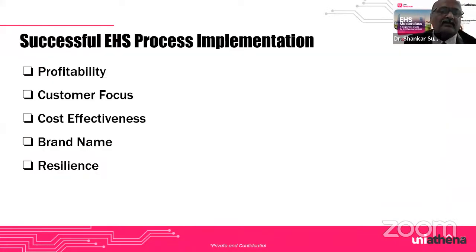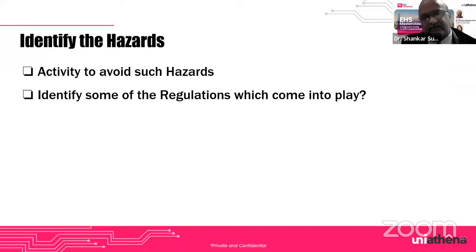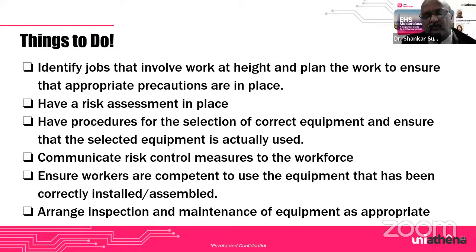So going back to this, what I meant is identifying the hazards. Okay, so when a situation is given, you can identify the hazards easily. And when you identify the hazards, you can identify the potential danger and avoid it. That's exactly called a risk assessment. So if you identify that things are lying in an unsystematic way, you make sure that it is all kept in a proper systematic manner, and you have a site supervisor who takes care of all these things. So there is a pathway where people can easily walk through, or the equipment can travel.